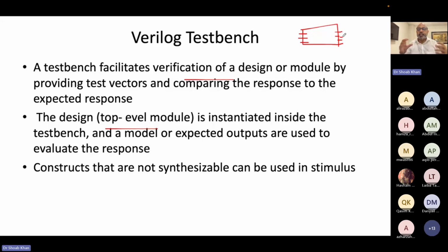So you have to be smart about how you can invoke different types of coverages, because there's logic which is going to have millions, sometimes billions, and now they're reaching a trillion transistors. So you are basically making every transistor switch from 0 to 1. You would not let any transistor sit idle while you are testing, and in a manner that covers all combinations. You can imagine that testing all combinations is not even possible if there are a trillion transistors in the hardware. So you have to be smart.